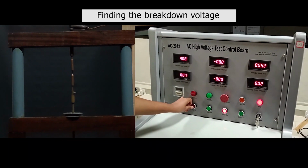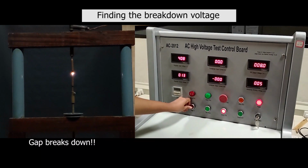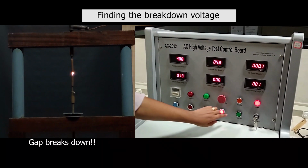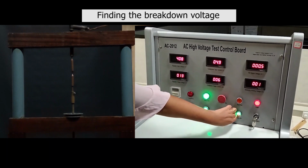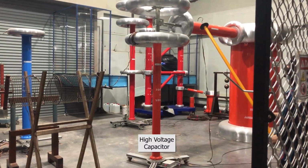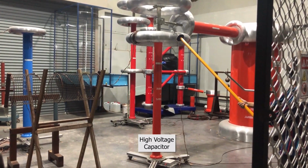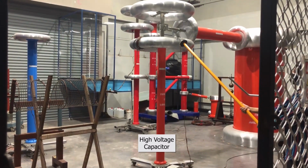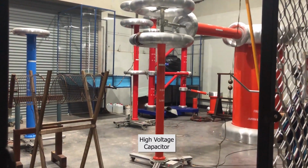As you can see, once the output voltage reaches a certain voltage, the gap breaks down. We note down the voltage at which the breakdown occurs. Before conducting the experiment for a different gap length, we must remember to discharge the high voltage capacitor like this.